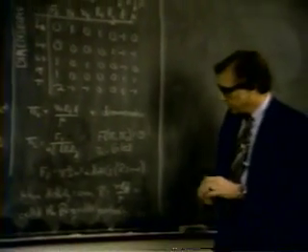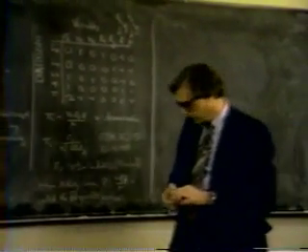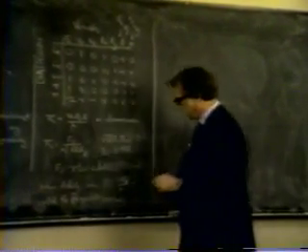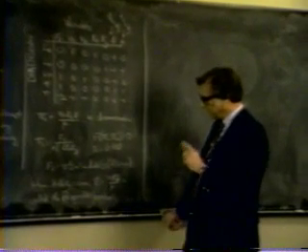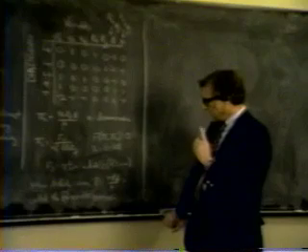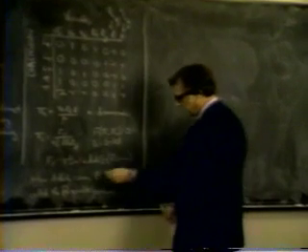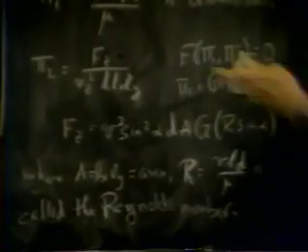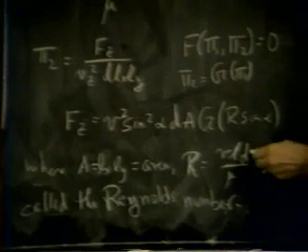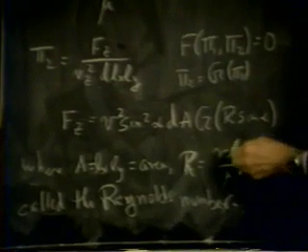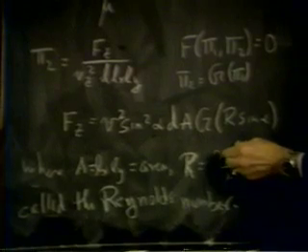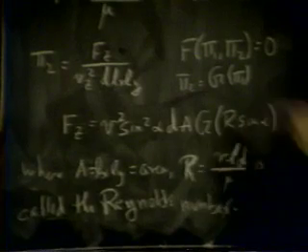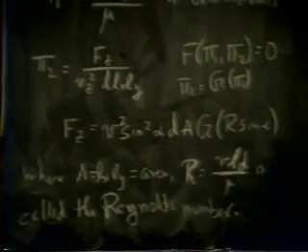And in fact, one can then proceed to the performance of the airfoil in a very simple kind of way, simple in principle. We can estimate for the air that the airplane will be flying at a certain altitude. We can compute its density. We have the typical length dimension of the airfoil. We can talk about the velocity that we're expecting to deal with and the viscosity of the air and get an estimate of the Reynolds number for the conditions of the flight.